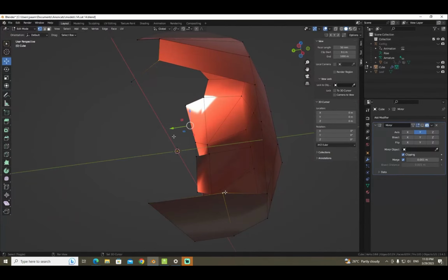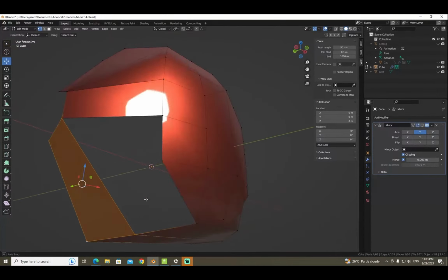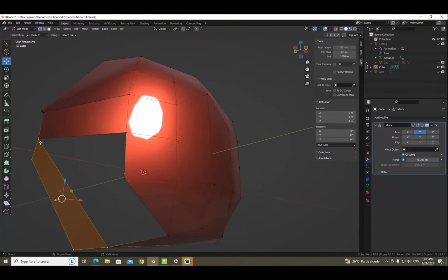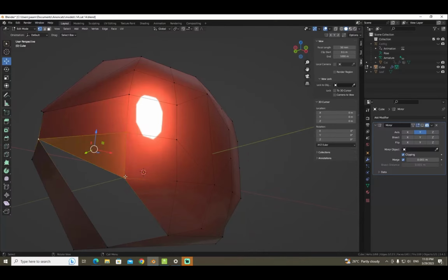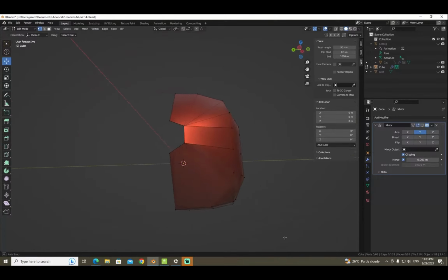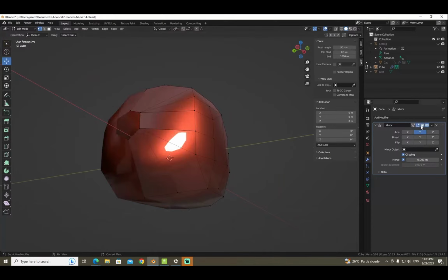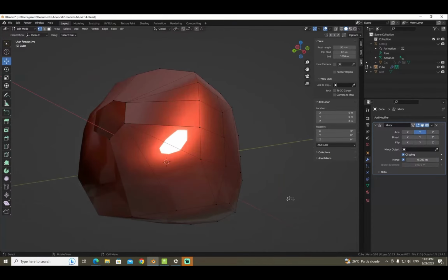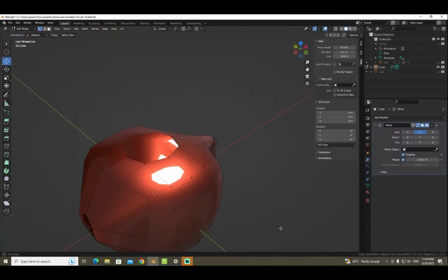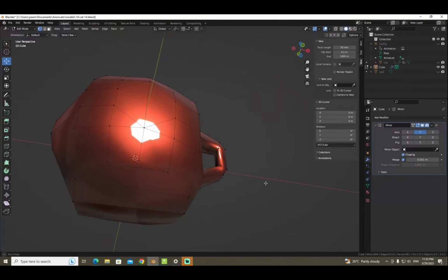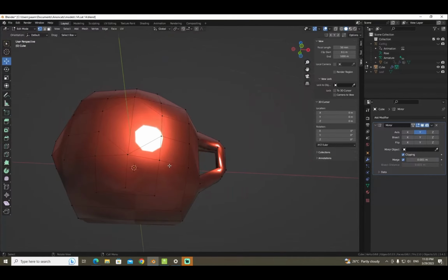Delete this vertex. Connect it here from the face. Now I have this fan structure here, and a quad here instead. Does this do anything? Okay, I save another 4 vertices here, so it's now 110 triangles. Okay, where else can I save?